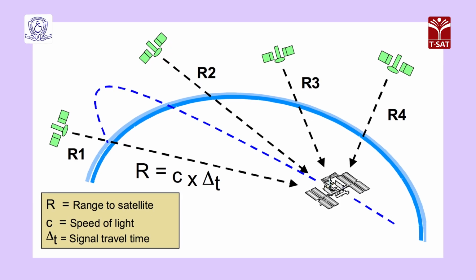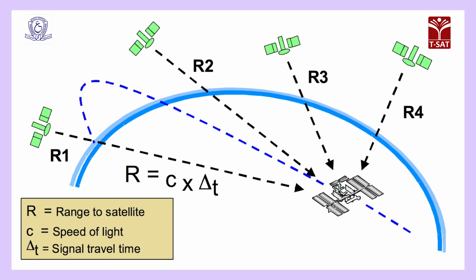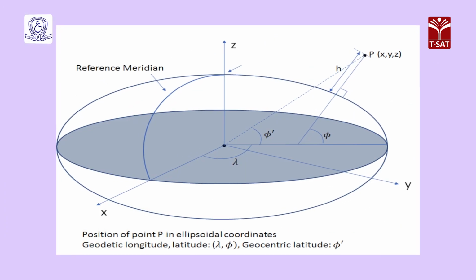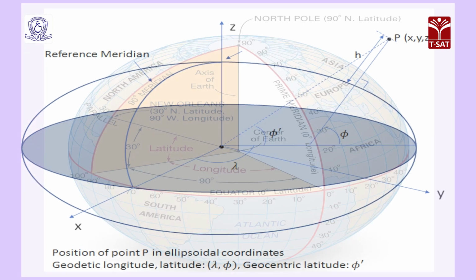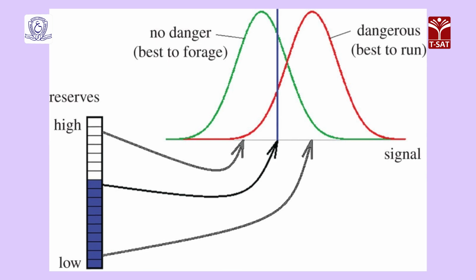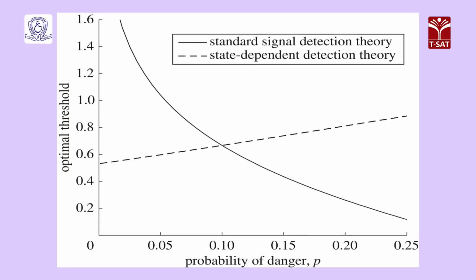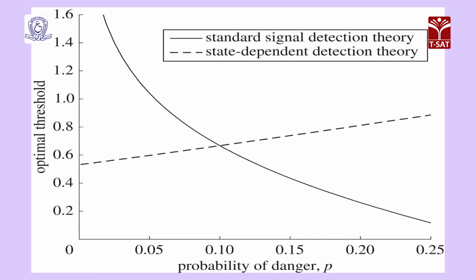With at least 4 satellites visible and their alignment good, the 4 spheres will intersect at only one point in space. So, the receiver position can be accurately fixed in 3 dimensions, 3D fixing, that is in latitude, longitude and altitude. With 5 satellites visible, it is possible for the system to automatically detect an erroneous signal. With 6 satellites visible, it is possible for the system to automatically detect an erroneous signal, identify which satellite is responsible and exclude it from consideration.